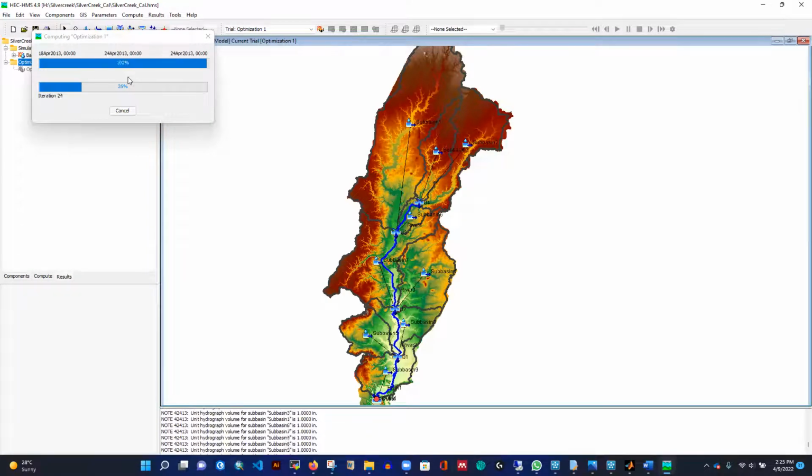So we have to fix that. Let's see if we can fix it. So what we're trying to do here is match the observation with the model generated hydrograph. But if you see, previously you saw the peak is pretty flat. So it's even challenging because we know the typical shape of a hydrograph: we have the rising limb, we have a recession limb, and we have the peak, right? But for this case, the peak is pretty flat, so it's pretty challenging to capture.